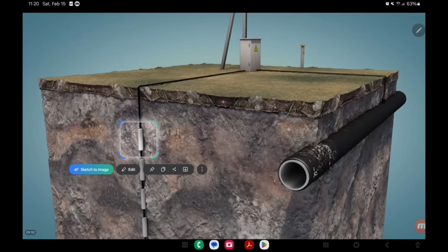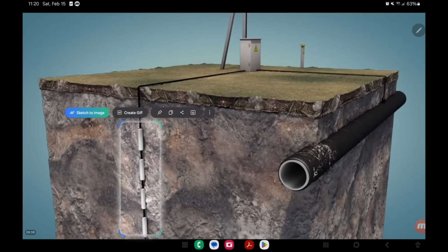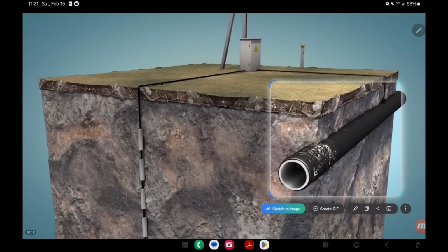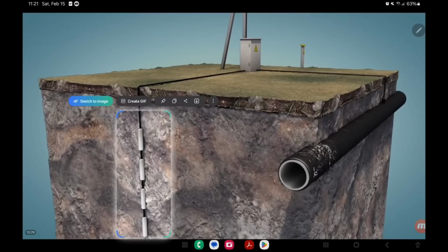That's why you will see that in our designs, the total resistance of this almost never exceeds 1 ohm. Why? Because we are talking about money. The more resistance it has, the more energy consumption, the more energy the client will have to use to supply the voltage and current we need to protect our pipeline. So basically, that is the reason why, in our calculations, we try to always keep the total resistance of our ground bed below 1 ohm.